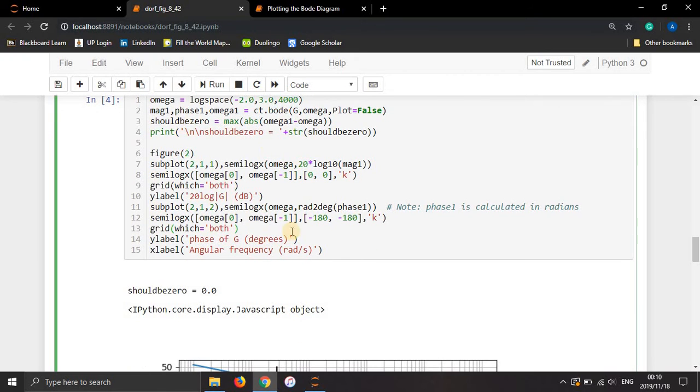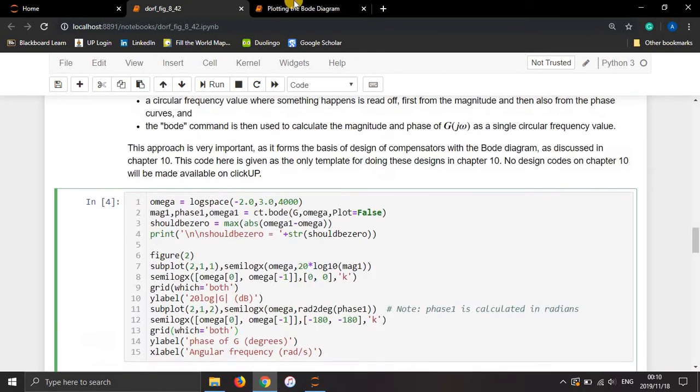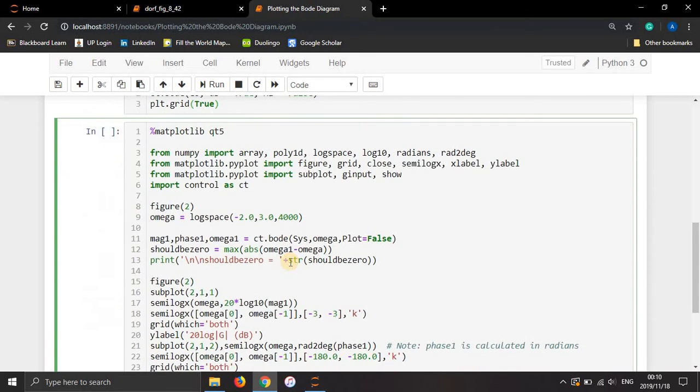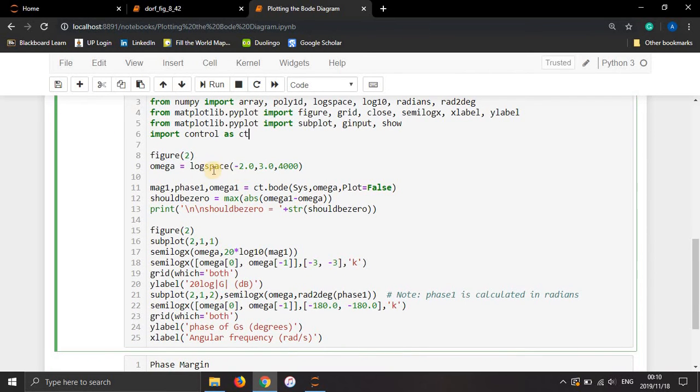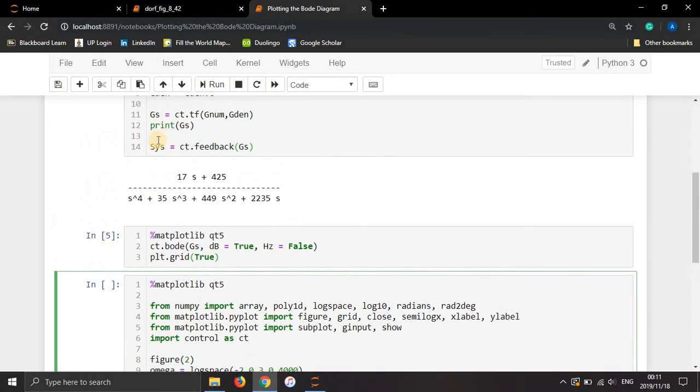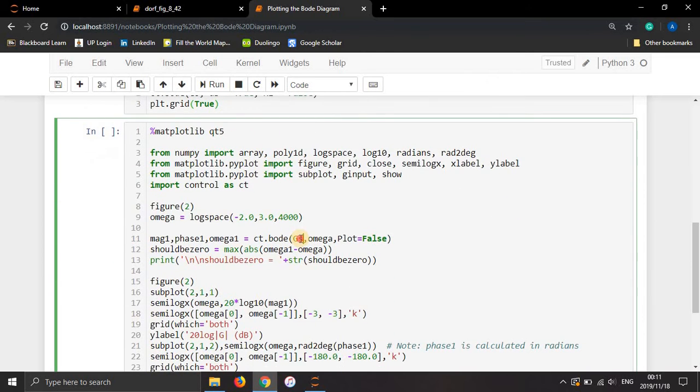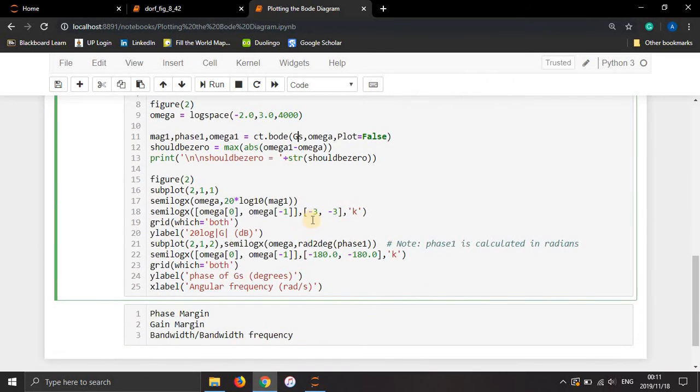Sorted. Okay, but we copy and paste this, and I've changed those already in this notebook. So here it is. Here you can see I've changed control.matlab to control, and gs should be somewhere here. Where's gs? Oh, I've done sys, so let's say gs. Okay, there's gs, and we've now changed it to gs, so that's the open loop transfer function. These two we want as 0.